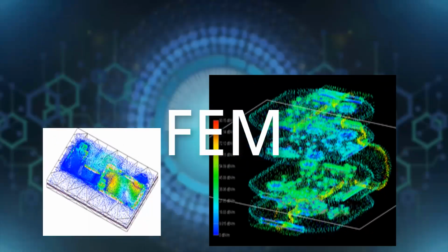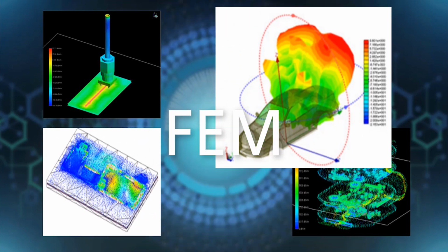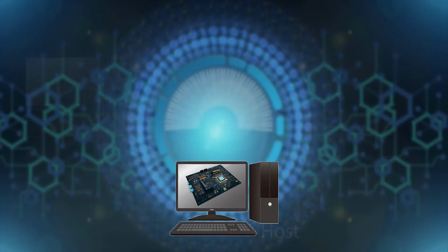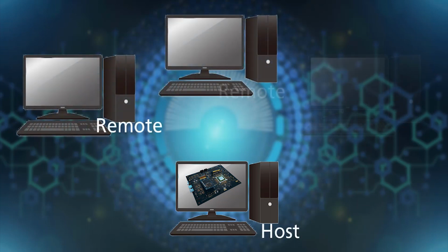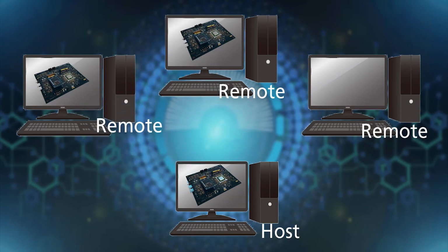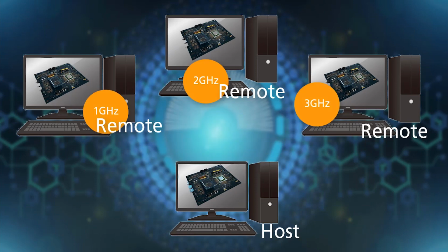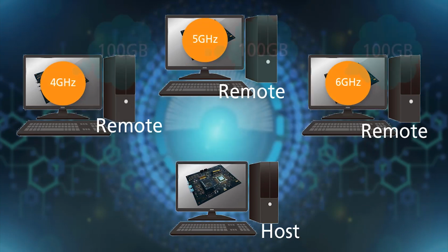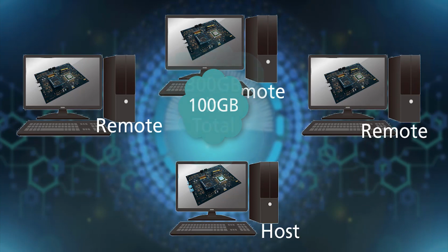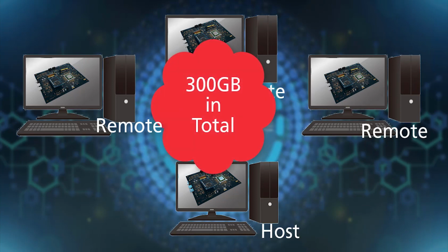Traditionally, there are two methods that have been taken in the distributed computing with finite element method. The first method is to submit a job from the host for each analysis frequency. In this method, the memory used by standalone environments and each machine during distributed computing will be the same. This increases the amount of simultaneously used memory, which leads to an increase in machine load.